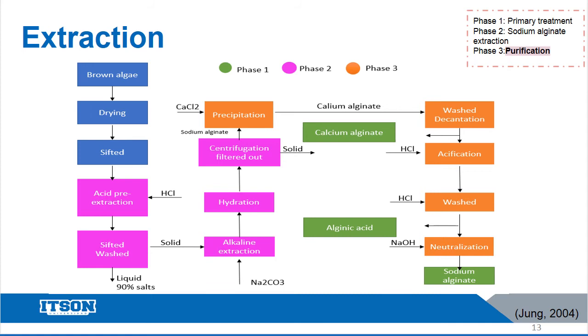Subsequently, the separation of the solid mass is carried out using a basket centrifuge, and at this point the sodium alginate is mixed with various elements that receive acid and base attack and separate in the same phase as this alginate. This is what is called crude sodium alginate. As a control of this stage, the viscosity of the filtrate is determined for the maceration carried out, each time.